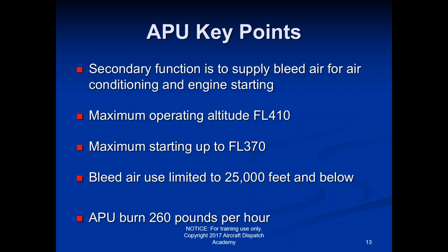There's an MEL, same thing. We'll look at MELs later too, but there's an MEL called an IDG MEL. IDG stands for Integrated Drive Generator, and that's basically your engine electrical generator. So you don't need to write that down right now, but we'll look at it later. But that's the engine generator. The APU serves as the auxiliary backup electrical generator when the engines are on. It's the primary generator when the engines are off on the ground, but in the air it's the backup. It's the first auxiliary backup generator.